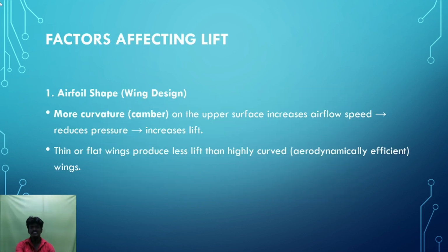What are the factors affecting lift? There are many factors affecting lift. First one is airfoil shape, that means wing design. The more curvature on the upper surface increases airflow speed and simultaneously reduces pressure. This pressure difference increases the lift. The more curvature means camber area.